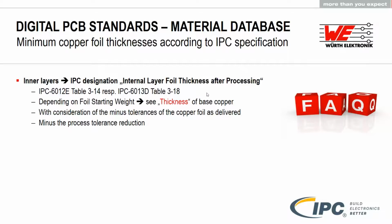So we have to consider that already in the calculation. And during the processing of the material, there are some cleaning and etching processes, and this could also reduce the thickness. So that's the calculation for inner layers.